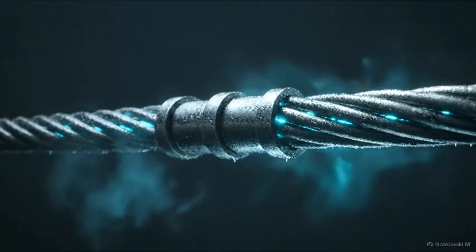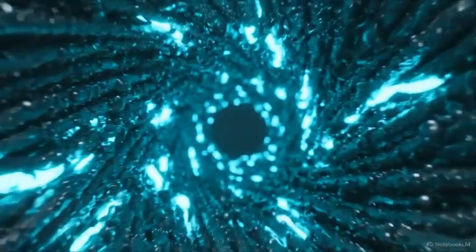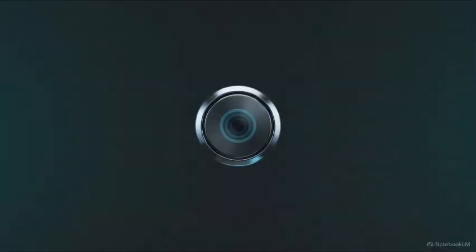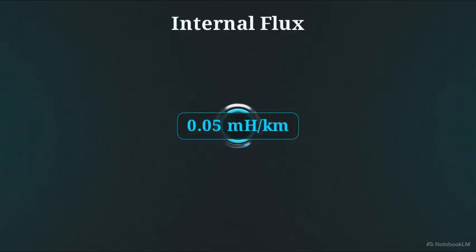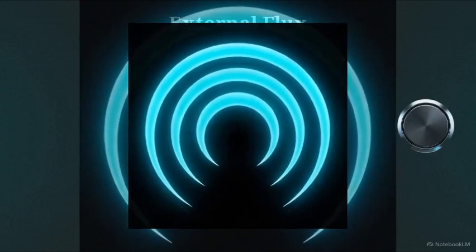To calculate that friction, we have to look inside the metal itself, where the magnetic field doesn't just exist on the outside. There are magnetic loops physically trapped inside the solid metal of the conductor. We call this internal flux. You might assume a thicker wire traps more magnetic force, but the math reveals a specific property. Assuming the current density is uniform, internal inductance is a fixed constant. It stays at 0.05 millihenries per kilometer, regardless of the cable's thickness.